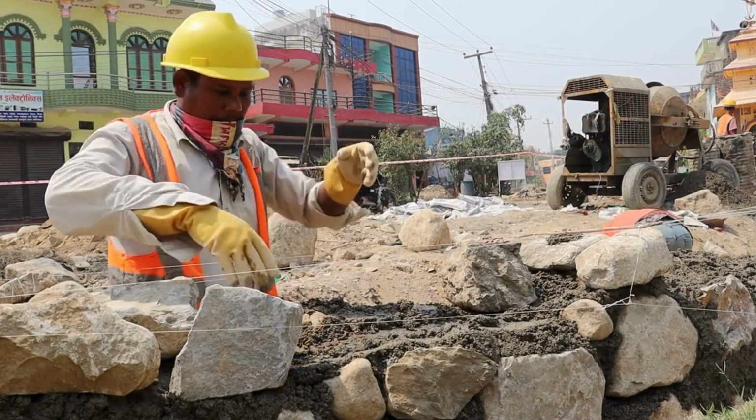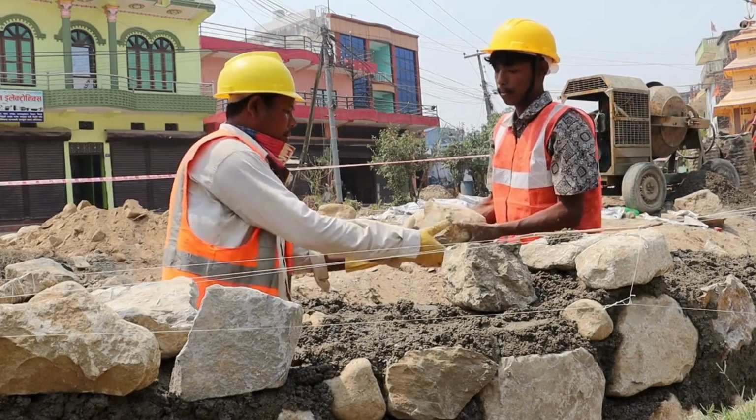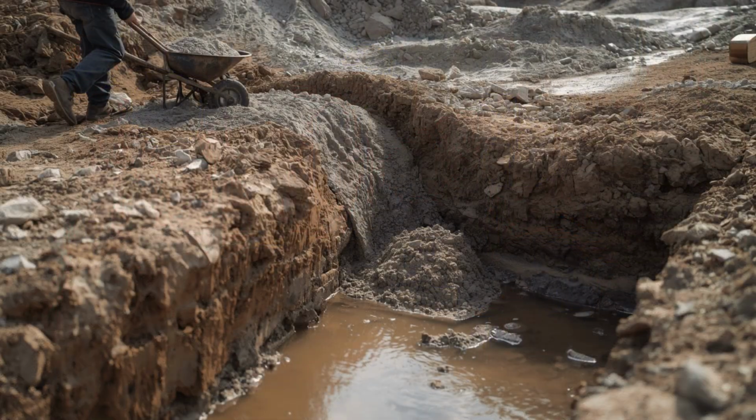However, a rubble foundation is only suitable when the soil has adequate bearing capacity. If the ground is made up of soft clay, loose soil, filled land, or any other weak soil with low bearing capacity, a rubble foundation alone may not be sufficient. In such cases, the ground must first be improved. This is usually done by excavating the weak soil to a suitable depth and replacing it with well-compacted material, such as quarry dust, quarry sand, gravel, or other approved fill materials, depending on the engineer's recommendation.